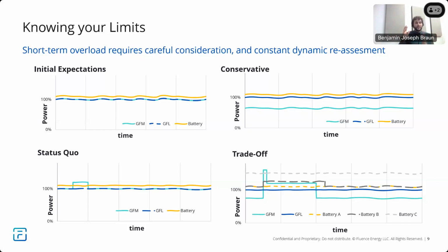And in order to do that safely, and for a manufacturer to say, yes, you can do it, and I don't have to have any concern about my hardware failing and then getting into warranty issues, many of those suppliers will say, right, in grid forming, you actually have to derate the amount of power capability you can do. Effectively, that creates a headroom for their controls, as shown here in the top right, very conservative,